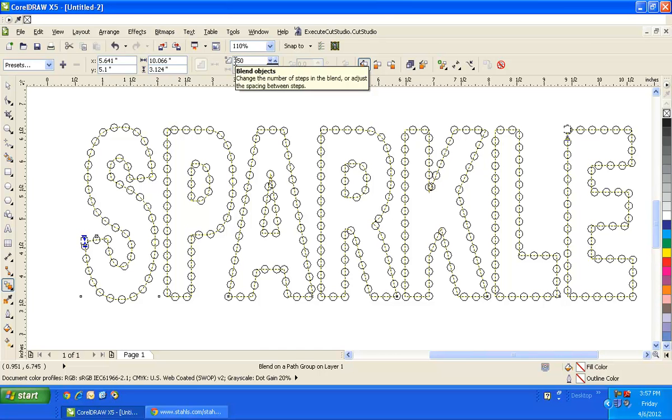But primarily, if you cut the circles too far apart or too close together, when you brush those stones on top of those holes to fall into place, they're going to get caught on the lip of the circle that it cut itself. So it's going to mean more production time. So you kind of just want a little bit less than the actual width of the circle itself.